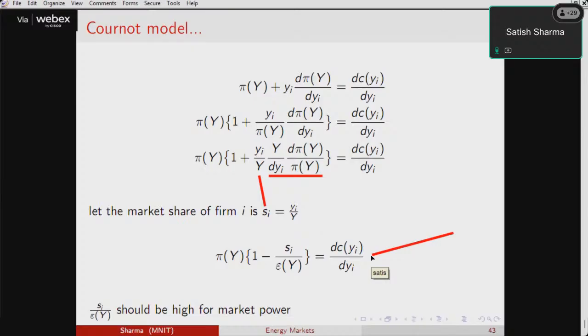And economic dispatch provides the same incremental cost for all the generators, provided no limit is being hit. If no limit of a generator is being hit, then the incremental cost, which is the same for all the generators, can also be used as a market clearing price, and that will be unbiased. True.